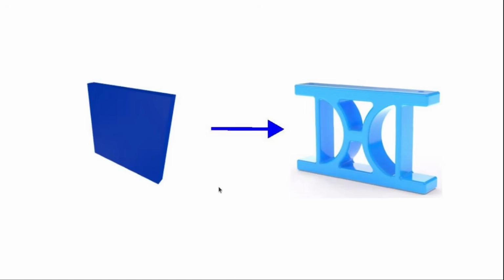Now, topology optimization finds the path along which the load is transferred from the load face down to the support and keeps material only along that load path and removes material elsewhere. So we get a lighter structure and it efficiently transfers load.